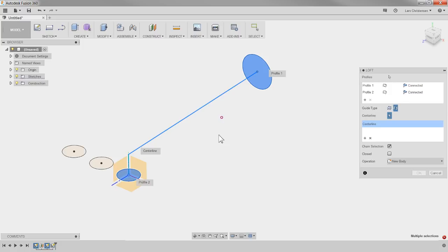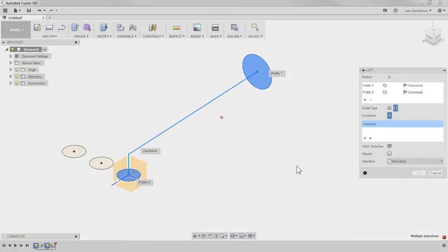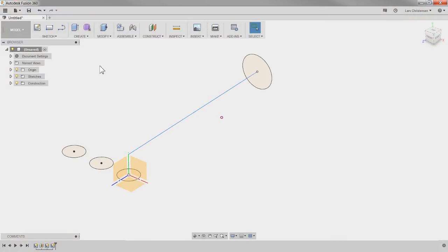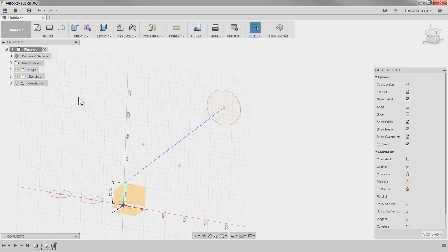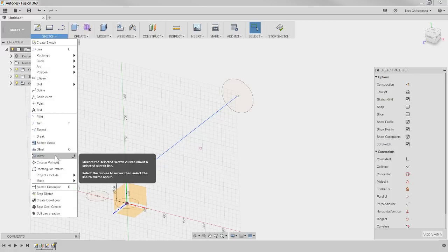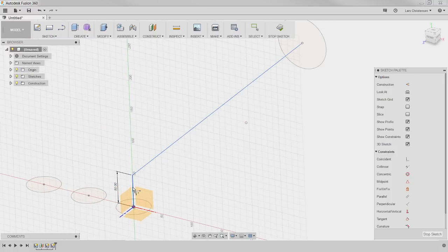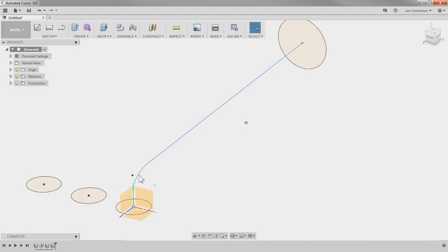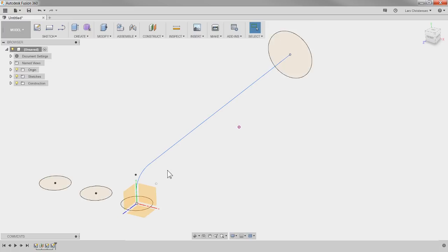Solid lofts do not like when the loft kinks, when it collapses in on itself. So it's looking for a smooth transition between the two angles. I hope I saved a little bit of frustration here. So if we go into that sketch we did the 3D sketch on, edit that sketch again, and we add a fillet. Now, I played with this before I got on the live stream, and I found that a 40 millimeter fillet worked here. It's got to be a big enough fillet that the thing doesn't collapse on itself.